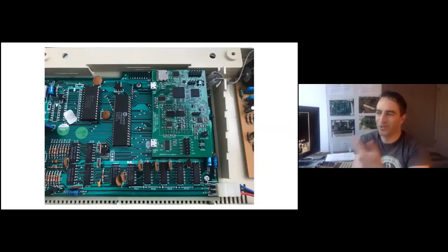So the bring up process for a board like this, you sort of start from the outside and you go in. I got some code running on the debug microcontroller, the chip in the bottom left corner, and then the FPGA, just something simple that would pass through the SPI connection from the microcontroller to the flash. Then I could verify that the flash was responding by talking to it from the microcontroller, and managed to program some stuff into it for use when I got everything else working.